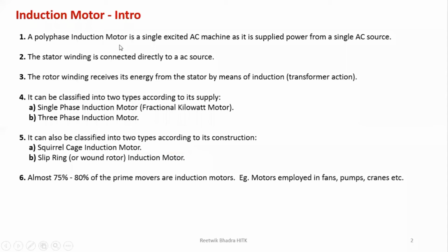A polyphase induction motor. Why polyphase? Polyphase because we are studying three-phase induction motor. So that's why the polyphase induction motor is a single excited AC machine. That means only one supply is needed. So it is supplied power from a single AC source. It is a three-phase supply. So one power supply, which is a three-phase supply, is required to give the power to the polyphase induction motor. So it is a single excited machine.